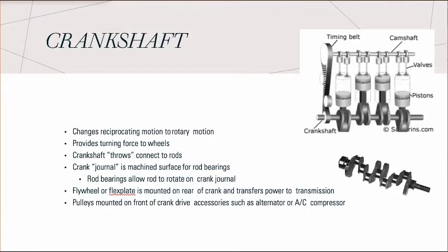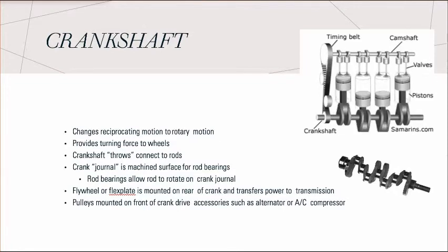A flywheel is often attached to the end of the crankshaft in order to store rotational energy and maintain a more consistent rotational speed, as the crankshaft receives energy from the connecting rod as a series of pulses. This assists in smoothing the power delivery, and is often used in conjunction with a harmonic damper, which attaches to the other end of the crankshaft to reduce torsional vibration.